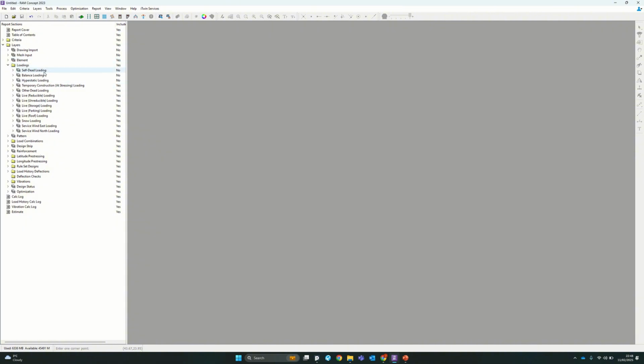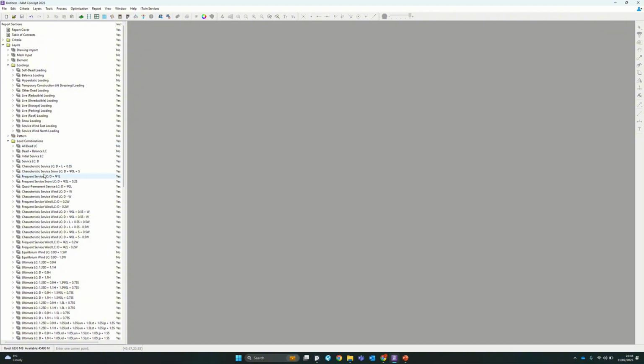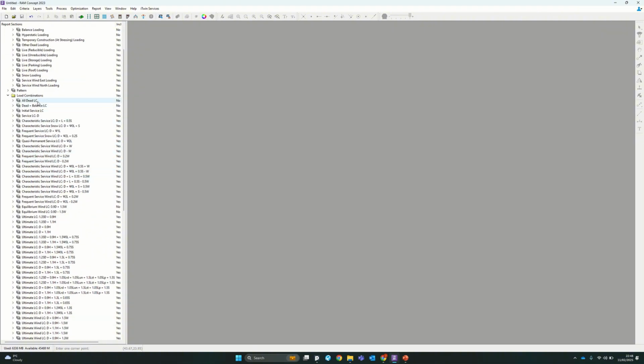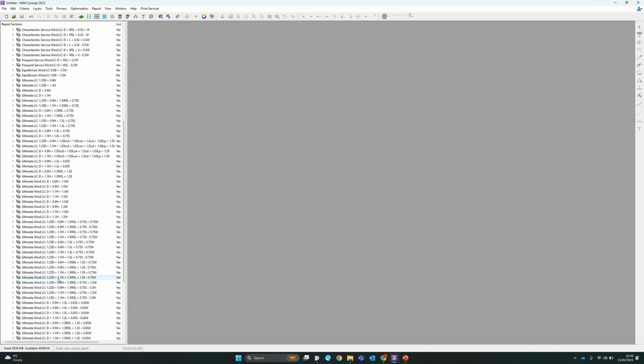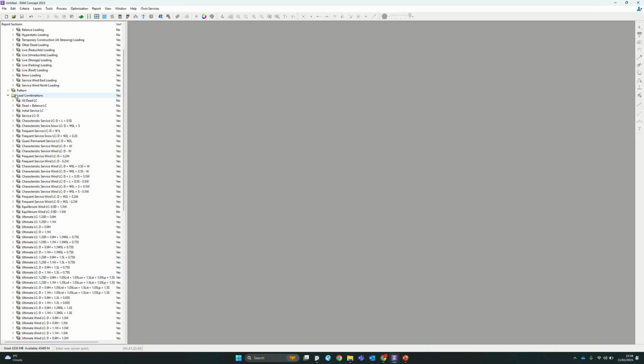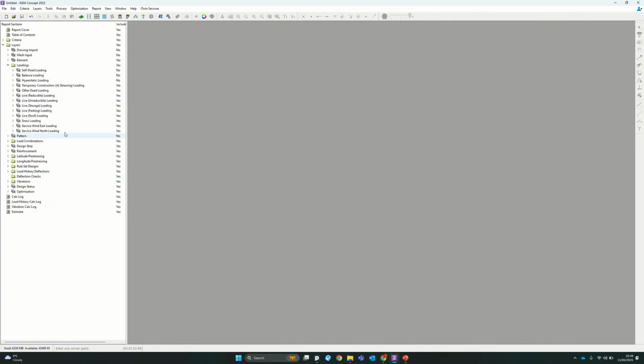This isn't something that I've done, these always come with it. I usually delete most of them and then try and rearrange it a bit to make it something that I want to put out there, but the same with the load combinations. Based on Eurocodes, it will automatically populate this table with a lot of load combinations. So within this then, for this sake, I'm going to go and add a live load.